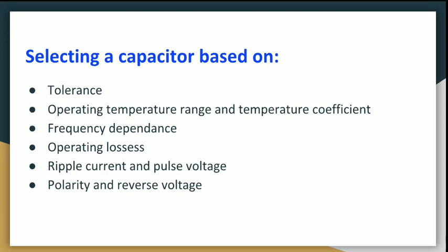If the circuit is temperature sensitive, or capacitance should not vary beyond a limit over a range of temperature, its operating temperature range and temperature coefficient must be taken into account. Based on the temperature coefficient and temperature curve, the extent of change in capacitance should be calculated. The temperature sensitivity of a circuit can also be dealt with by using capacitors of positive and negative temperature coefficients together. In that case too, the maximum variation of capacitance over a range of temperature must be calculated.